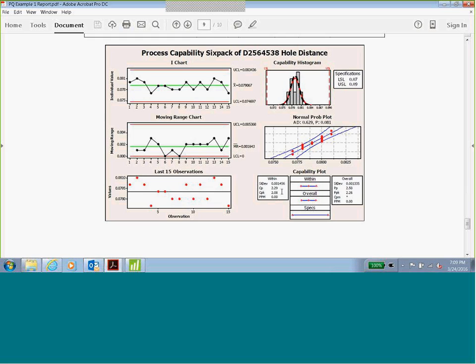Sometimes you will not be doing any type of capability analysis. So just in your PQ study you're going to be doing the capability analysis and interpreting your results using the Ppk value. But again, it's just information. It's going to depend on how the company follows their procedure, and all OQ and PQ may have this process capability analysis.